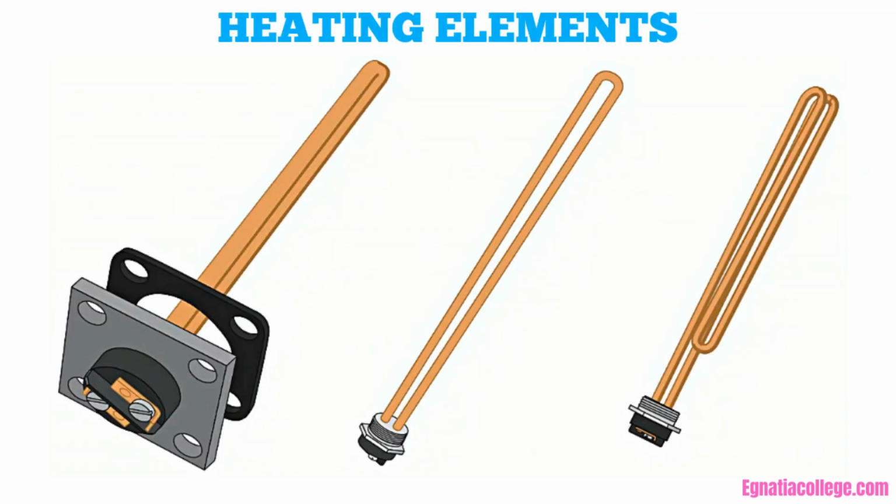Heating elements. The wattage ratings of electric water heaters vary greatly, depending on the size of the heater in liters, the speed of recovery desired, local electric utility regulations, and local plumbing and building codes. Wattage ratings are usually 1,650, 2,000, 2,500, 3,000, 3,800, 4,500, or 5,500 watts. Other wattage ratings are available. The heating elements are generally rated 240 volts. Elements are also available with 120 volt ratings and 208 volt ratings.